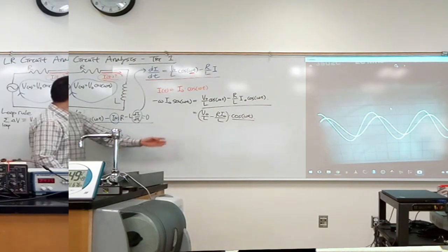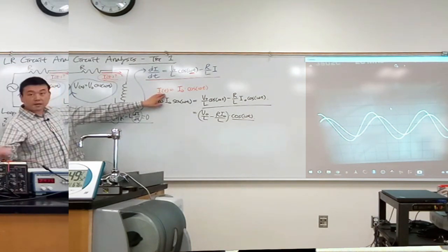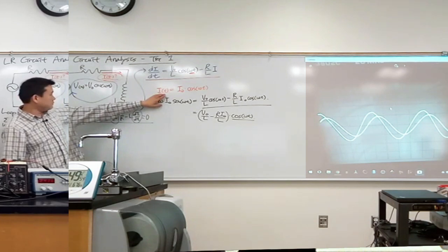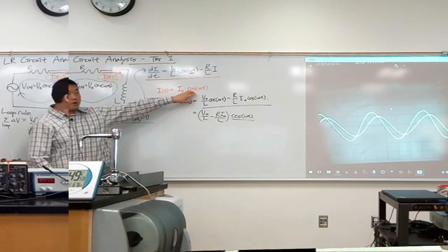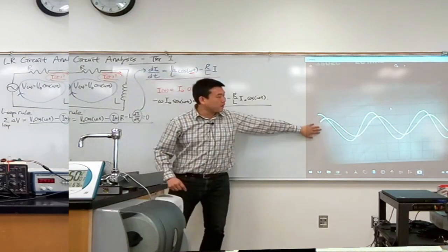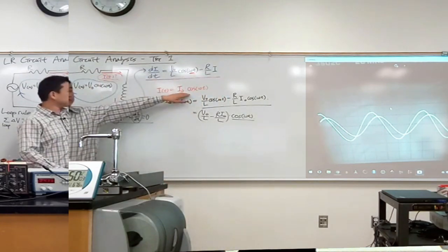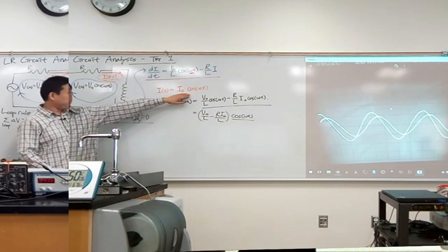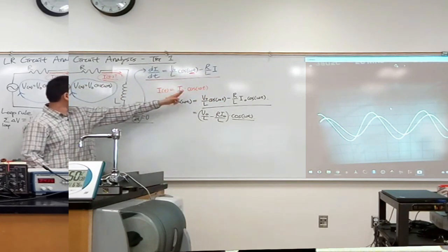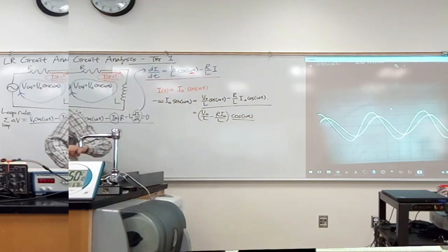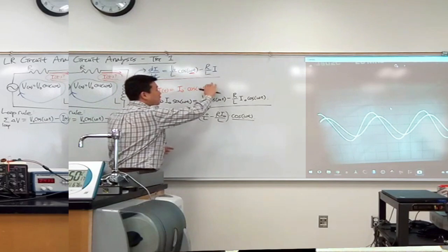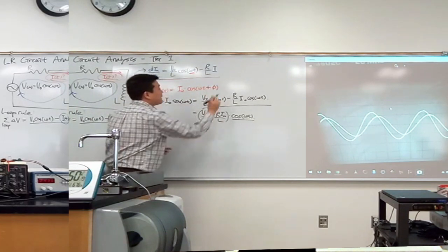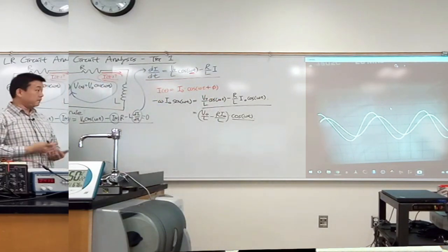This current is still something oscillating, so it should be possible to describe it with cosines and sines. What I'm hoping this is making you realize is that our guessed solution was missing one term. It's not just cosine of omega t, but I have to include a phase factor to account for the possibility that the current will not have the same phase as the applied voltage.